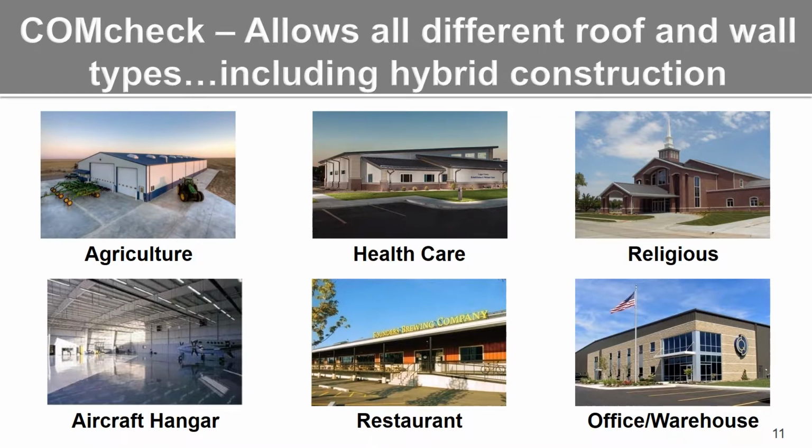As it relates to metal buildings, you may not have your traditional metal cladded roof and wall system like in the upper left-hand corner. You may have some brick wainscoting and stucco and maybe steel studded walls, although you may have the metal building primary frames and a traditional metal building roof with purlins or secondary framing members, along with a standing seam roof or a through-fastened roof.